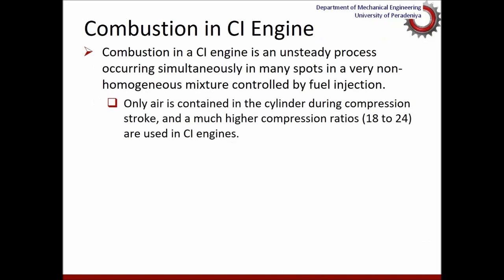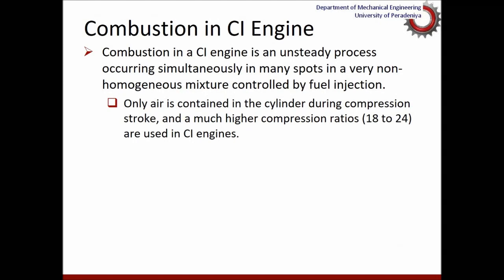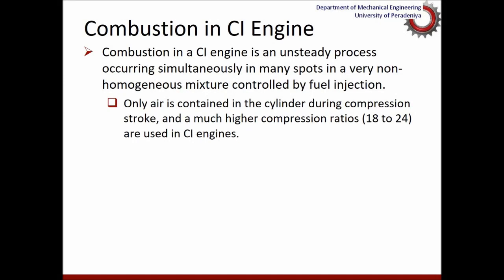Okay, let's move on to combustion in compression ignition engines, that is diesel combustion, which is somewhat different from combustion in gasoline engines, which is a pre-mixed combustion where air and fuel are mixed together well before the ignition takes place. But in the case of diesels, of course, we inject fuel at the end of the compression stroke.